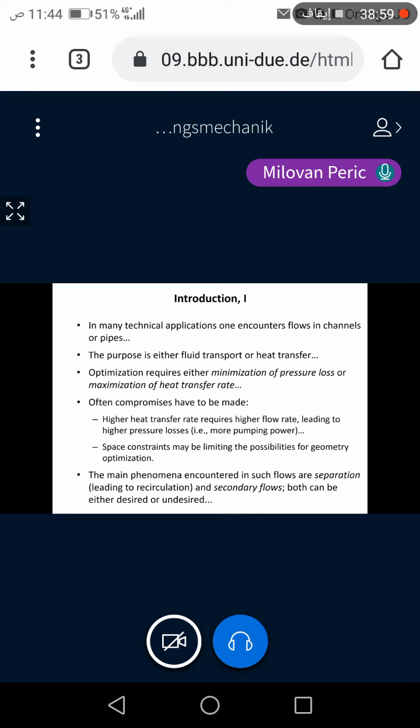For example, the 90-degree bend that I mentioned earlier, if you wanted to get higher, more homogeneous flow at the exit and smaller resistance, you would need to make larger distance between inlet and outlet and so on. But very often you have a limited space, so this space limitation is what is always constraining such optimizations.